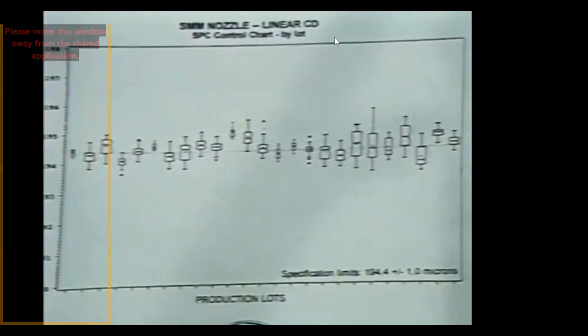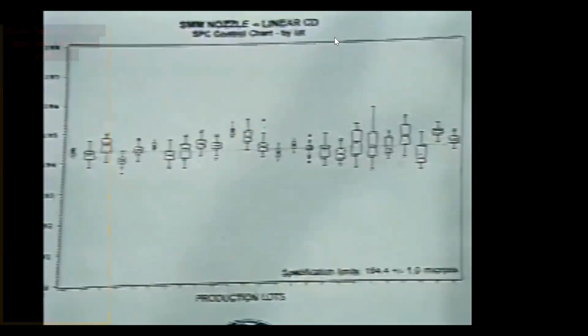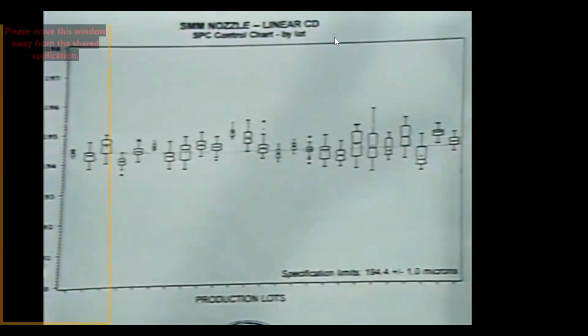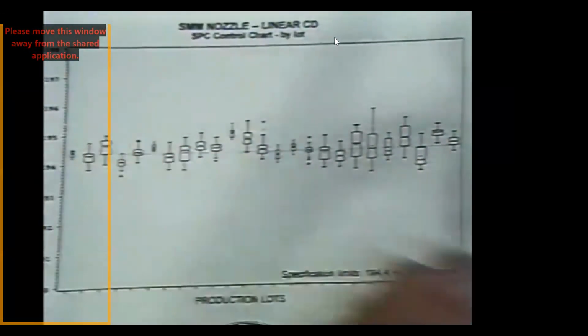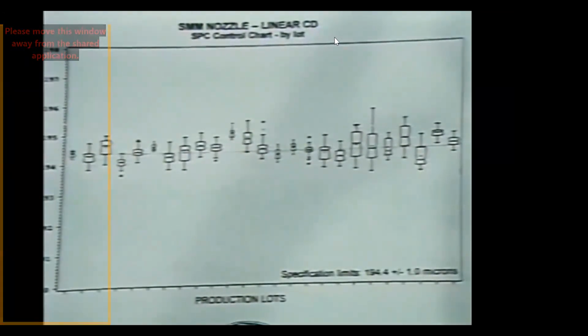Our inspection equipment had gauge capability down to 1/4 of a micron. So we would inspect every single orifice automatically. You'd load this machine, step through, and acquire data. Those units that exceeded the specification were rejected. Our typical lot yield was on the order of 60 to 80%. This particular lot represents about 50 wafers worth of material, and there's 400 units on a wafer at 4 nozzles per wafer, so there's an awful lot of measurements associated with that.